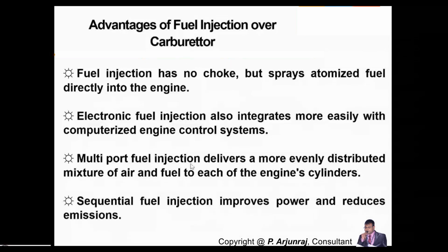And even this is not possible in the case of single point also. That is possible only in the case of the multi-point or multi-port fuel injection system. And again, the fuel injection is sequential. It improves the power and it reduces emission, which is not happening in the case of a carburetor. So that is the reason why we are going from carburetor towards the fuel injection system.